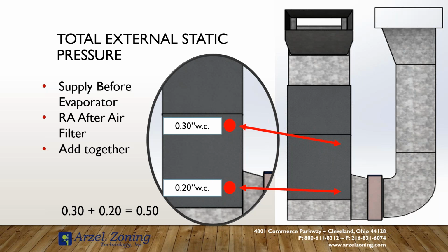his remarks were because of the way the zoning works, in that it allows the motor to start against a low static and ramp up to the high static, but then ramp back down for the off cycle. It allows it to start and stop against an appropriate amount of back pressure, and that doesn't damage the motor. And because it's able to ramp up safely and ramp back down safely, we're not going to damage the motor by exceeding that static pressure rating because of the way it works.